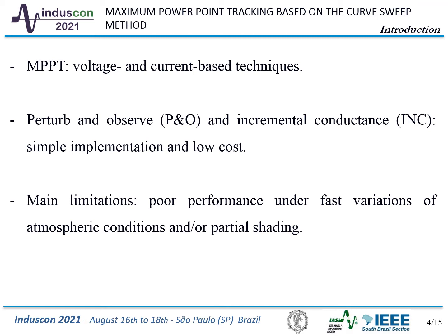The literature presents a plethora of solutions for achieving MPPT. Possibly, P&O and INC are two of the most popular solutions which allow determining the maximum power point. However, both techniques present some limitations in special conditions. The techniques present poor performance when fast variations occur in the climatic conditions. This may lead to the oscillatory behavior of the extracted power and reduction of the efficiency. Besides, both techniques may be trapped around a local maximum when partial shading comes to occur. Thus, it may not be possible to determine the global maximum power point accurately.